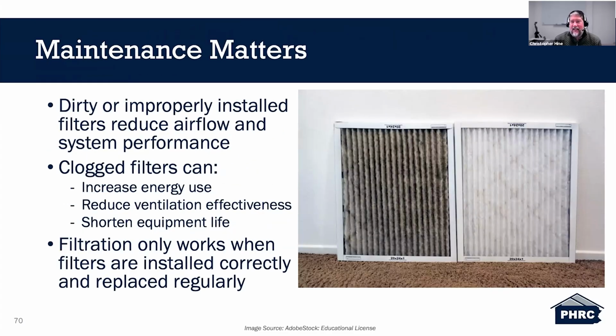Not only do you have to have filtration, but you have to properly maintain it, right? You can see here the image on the right has a dirty and a clean filter. That dirty filter probably is not doing a very good job at allowing air to pass through it, and it's probably not doing the best job at filtering. So there is a maintenance component to this as well.